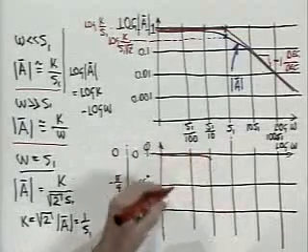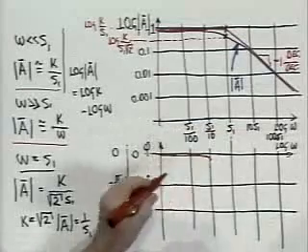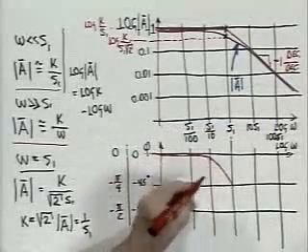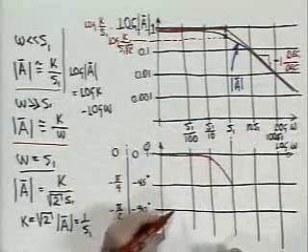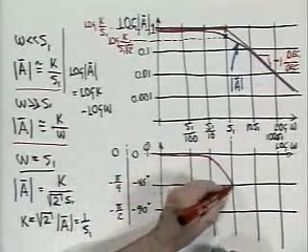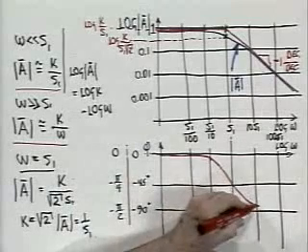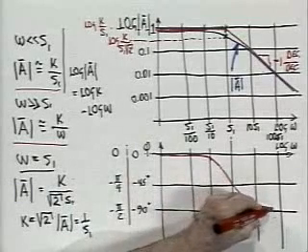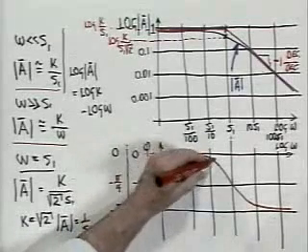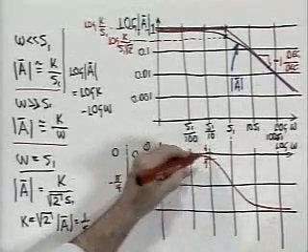When I get to the angle whose tangent is 1, when omega equals S1, the angle is 45 degrees. So it goes through that point. And then at 1 decade on the other side, this is a symmetric relationship in frequency, it's about 6 degrees away from its asymptote, which is minus 90 degrees. So to say it again, this distance is about 6 degrees.